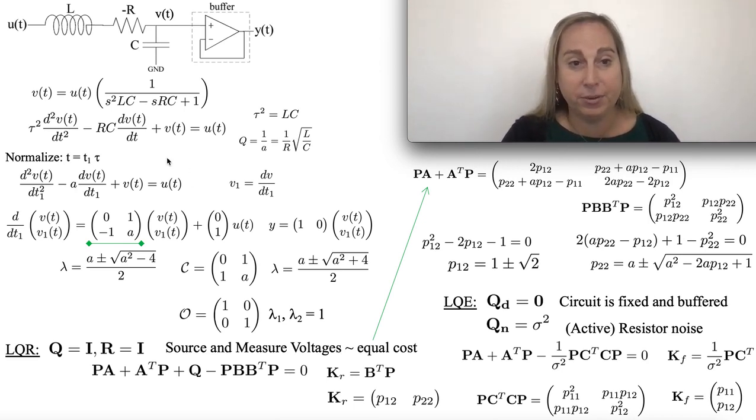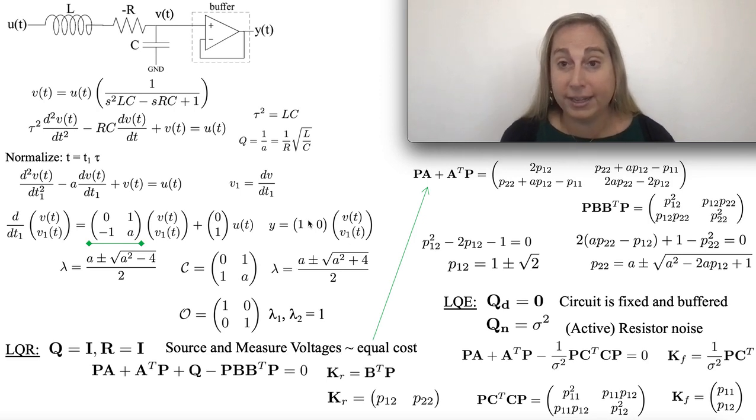So once I start with this equation, the question is, can I go into a linear equation system? Well, I'm going to define y1 as the derivative dv/dt. This allows me to deal with the second order term. As a result, I can write down a vector and then write down my linear equation system. I'm going to have my state matrix A, and a B matrix because I have the one input. It affects the one term and not the other. And then I'm going to have my C matrix. There's no feedthrough here, just my C matrix on this particular term. Great, so now I have the system defined.